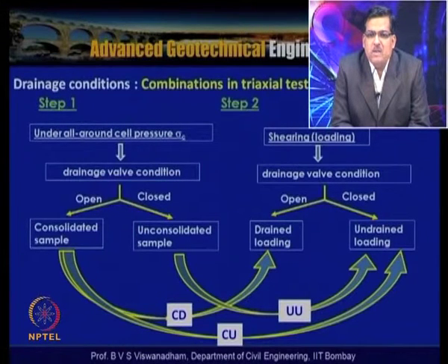We have certain practical considerations in which we will be doing the consolidated drained, consolidated undrained and unconsolidated undrained triaxial tests. For example, for the unconsolidated undrained triaxial test, consider constructing an embankment on soft soil without any waiting period, which means you do not allow consolidation to take place, not even during the shear. A rapid construction on a soft clay deposit simulates the unconsolidated undrained condition, and rapid loading of a foundation on a saturated undrained clay is also an example of the unconsolidated undrained test.